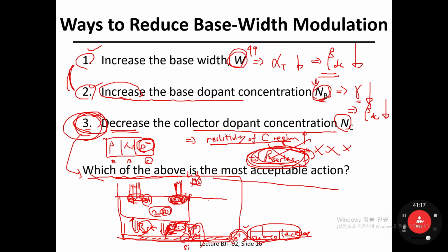And the bottom side is definitely silicon substrate. Okay, so for a given silicon substrate, you're going to first fabricate P plus sub-collector, and beyond it, collector p-type region, and a kind of N-well. It looks like an N-well in CMOS fabrication, so N-type base and P plus emitter. And definitely this tap cell is necessary to have an ohmic contact between metal M1 and the contact.